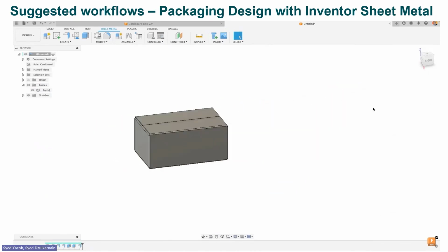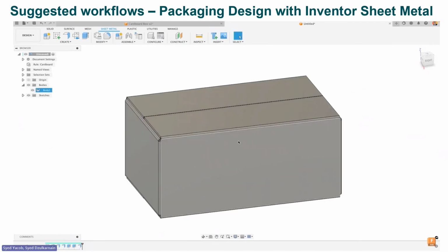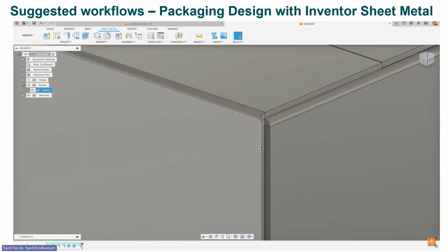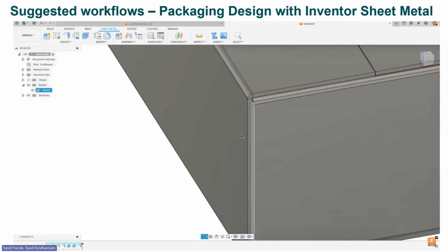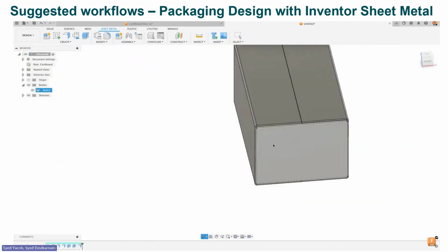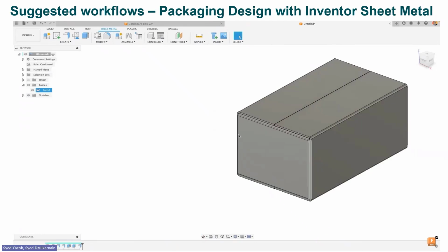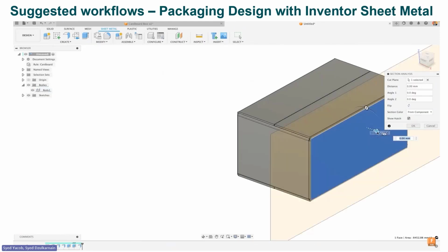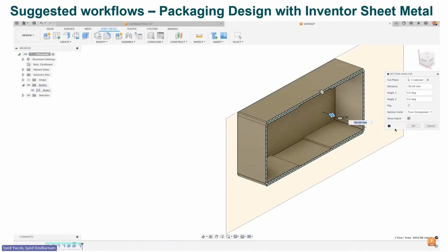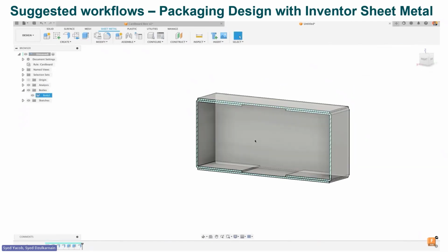So you can see it automatically creates a flat pattern, so that we can automate how our machine later on needs to cut all these flat patterns, right? Obviously you will have one very big raw material, usually a roll of material, so you need to cut this profile into that raw material. You can later simulate how many boxes you can get from maybe 5 meters of length. So you can simulate all that.